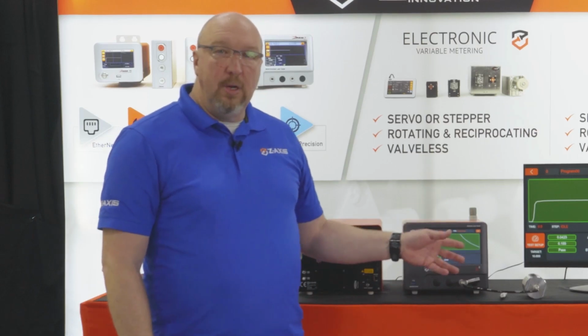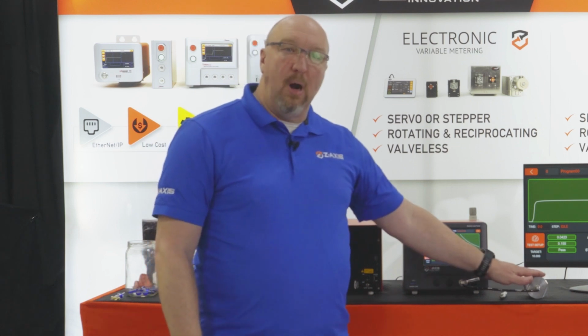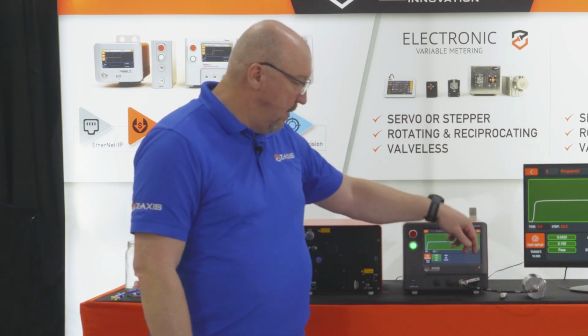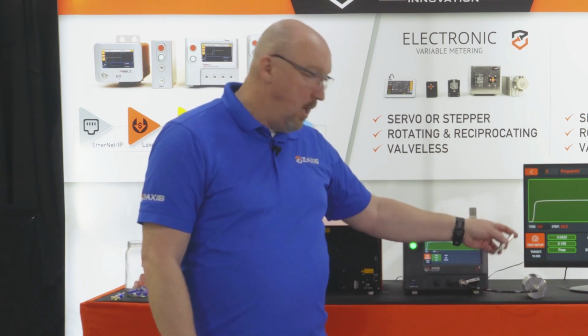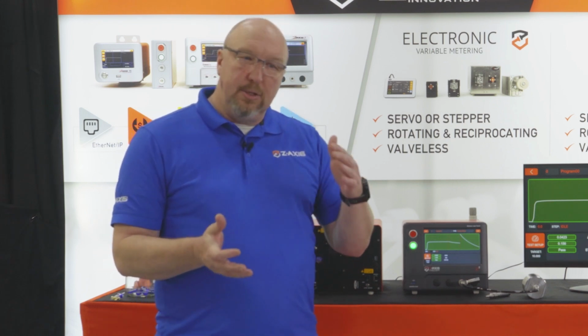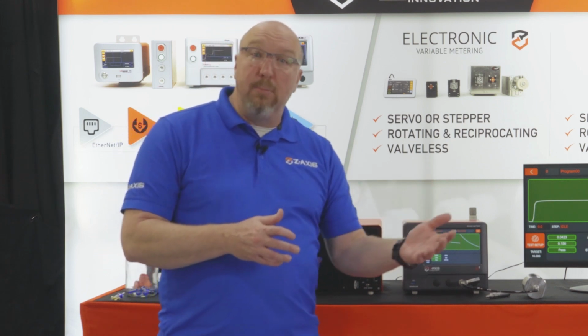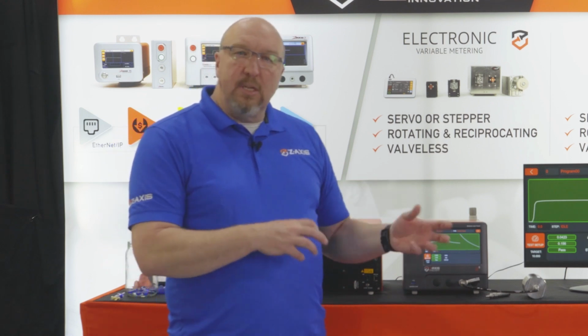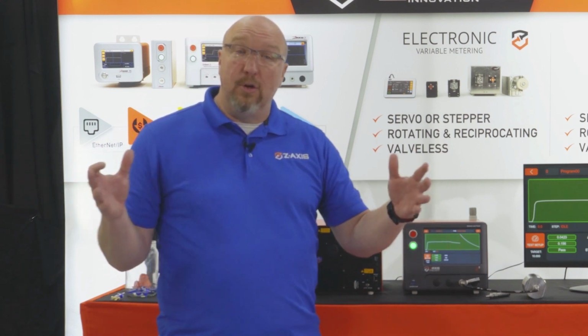Now that we've shown that we can test the master part by itself and we get the decay, and we test the part again with a known leak rate value on it, we can see the difference between those two values. And we can see that there's not quite enough separation to draw a line in between and declare one part good and one part bad. We're not following the 3x separation rule. What do we do? What we can do is start to manipulate times in the test to allow us to get those values to grow.